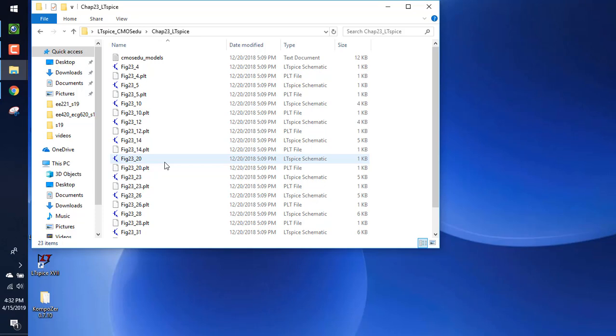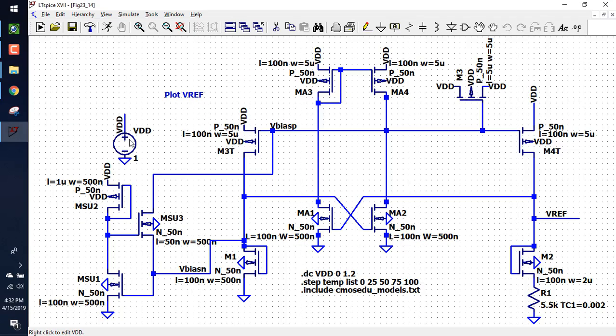That's weird. I guess I just have the result 2314. Okay, so this one uses an amplifier here. Do you think that's going to matter? No, not really. The temperature will change the gain of the amplifier, but it really won't have much impact on the overall currents. It'll be set just by what we just derived.